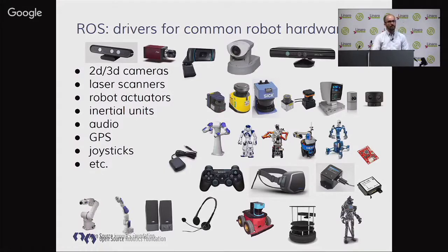The same thing goes for laser scanners. There are many, many different ones. There are the big ones that spin on top of autonomous cars. There are much smaller ones intended for smaller warehousing or research robots. All those things look the same to ROS now. You can write abstract, high-level logic code, which just receives these abstract messages. And the same could go on for other classes of devices and hardware.